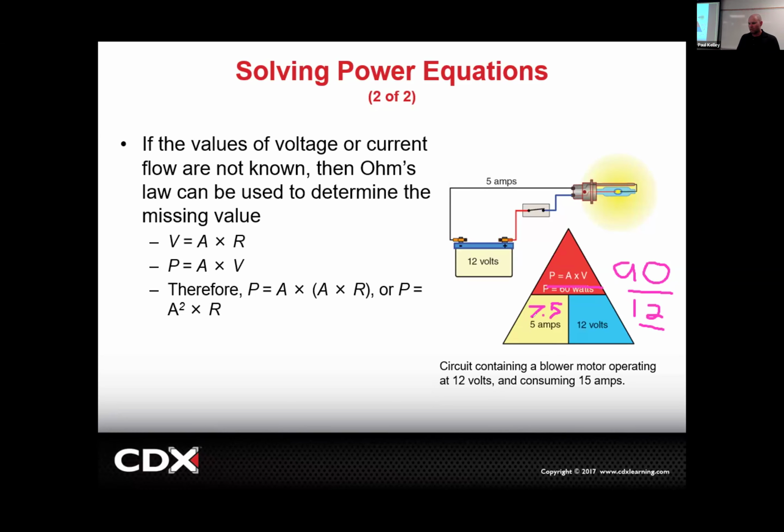Now, if they have a bulb, let's say it happens to be an LED, and they say, hey, look, we can make your 60-watt bulb have the output of a 90-watt bulb, but we can have your amperage actually be lower at 1 amp, I'm interested. Because there's no negative to lower amperage. You're using less electricity out of the alternator, less stress on the switch, everything, but you're getting more light. How is that? Well, LEDs are just a better, newer technology. Now, there's a bit of a negative. A lot of times LEDs come with a little fan to cool them. Other times they come with heat sinks and stuff like that.